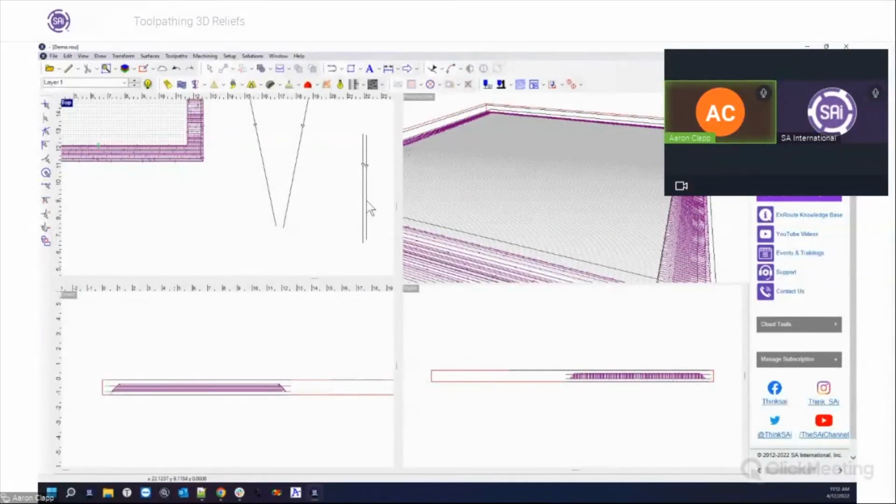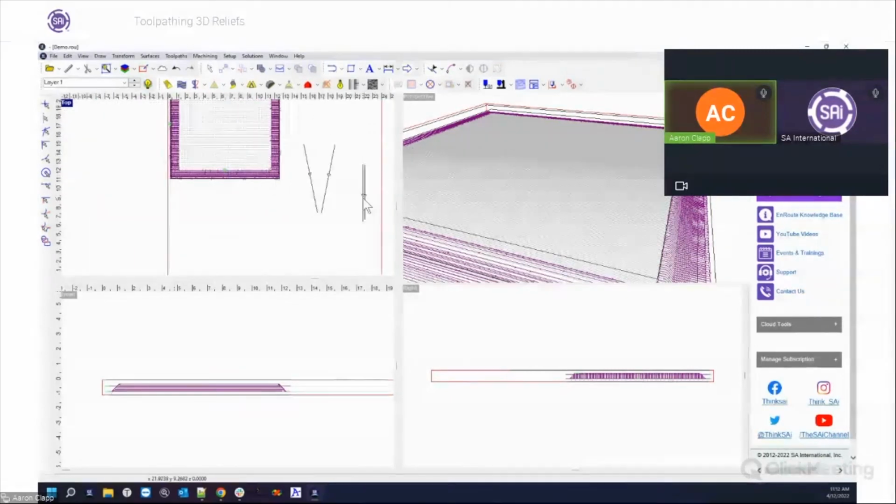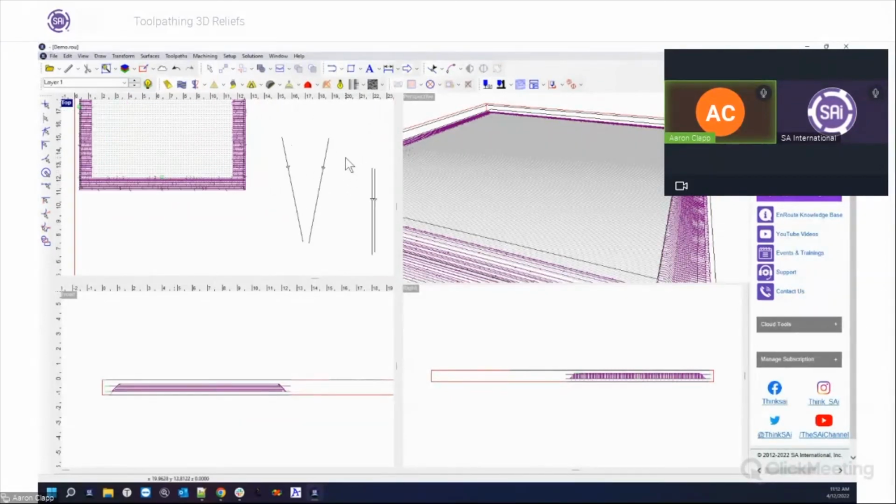So what you can actually get is some deflection, or the other problem that a lot of people run into with these tools is they just break really easily. So you almost have to babysit them along. So if you're going to get a 1/8 or a 1/16 or a 3/32 inch tool to cut really fine stuff, I would consider getting one of these tapered 1/8" end mills that have a little ball at the end. They're a little more resilient, they're a little stronger.